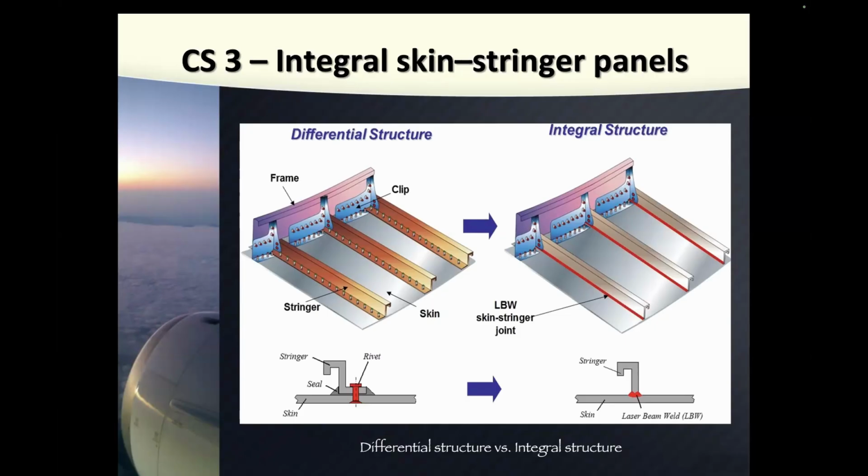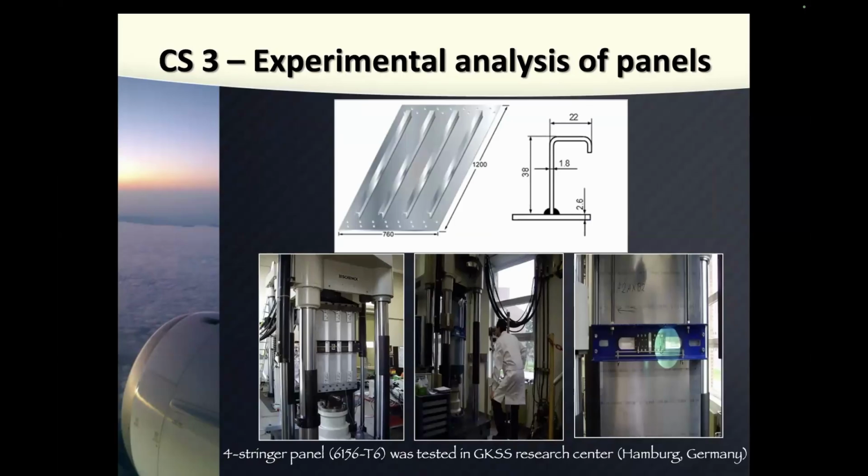And during design of the Airbus, one institute in Germany, in Hamburg, called GKSS Research Center, worked together with Airbus on fatigue analysis of these skin-stringer panels. And you can see here the shape and dimensions of the stringer. So this is the device they used for experimental investigation of crack growth in these panels.